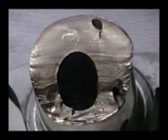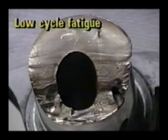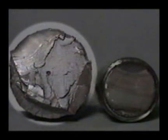Another good indicator of excessive cyclic loading is low cycle fatigue. Low cycle fatigue produces rougher, darker fatigue surfaces with prominent, wide-spaced beach marks and larger final fractures. Which of these two fractures do you think experienced excessive cyclic loading? If you said the one on the left, you're correct, because it is the one with the rougher surface, more widely spaced beach marks, and larger final fracture.